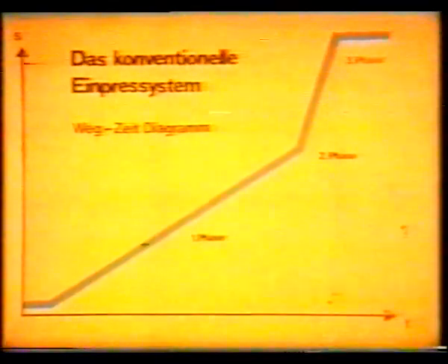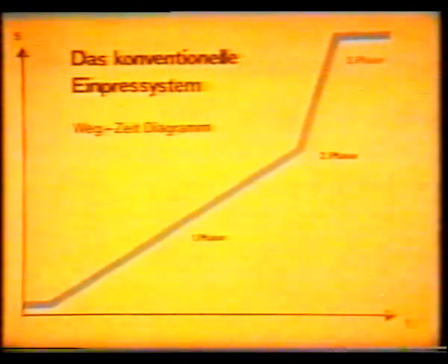The time-distance diagram of the conventional injection system shows the characteristic slow approach movement with constant speed during the first phase. The linear movement causes a disturbing turbulence within the sleeve. With the filling procedure of the injection system, as it is generally practiced nowadays, a wave is formed at the beginning of the injection movement, which breaks away from the plunger, hits a wall at the end of the sleeve, and closes the gate area. The enclosed air cannot escape anymore and mingles with the liquid metal. The resulting porosity has a disadvantageous influence on the quality of the casting.